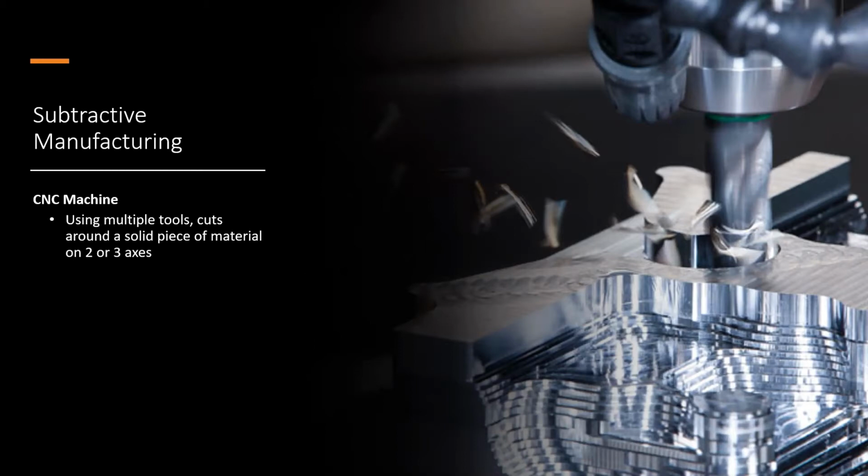Depending on how complex the object is that you're trying to create will determine how many axes you need. Do you need just a horizontal and vertical component, or do you also need a component where the axis can come in from the side? As you add more axes to the machine, they get more and more expensive, but you can also create more unique shapes depending on how many axes you can pivot your tools onto. But the big call out with CNC is that it's using tools and it's physically cutting away that material.